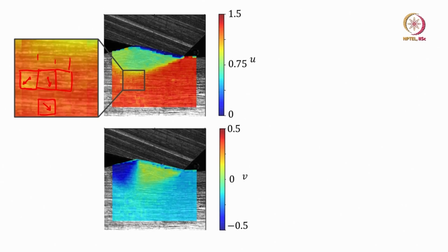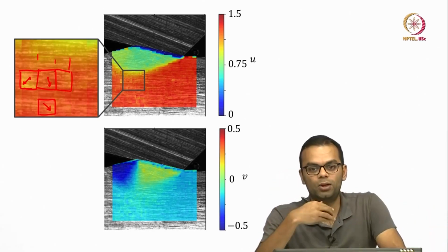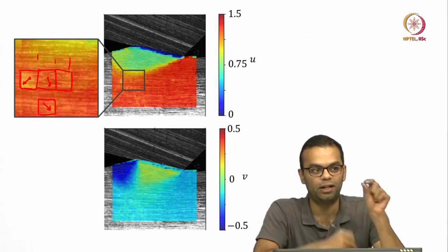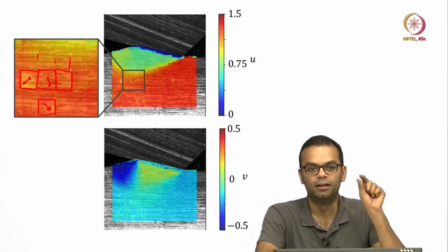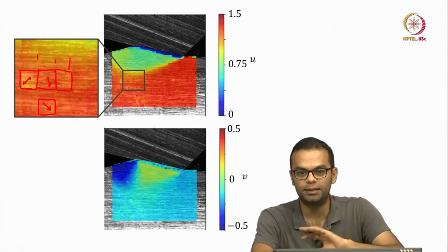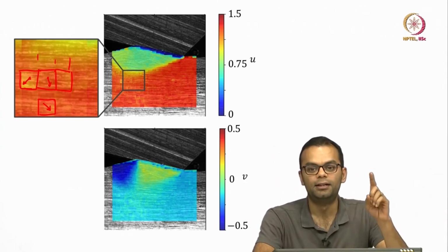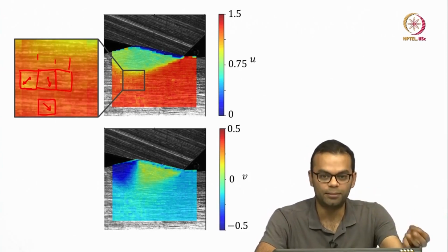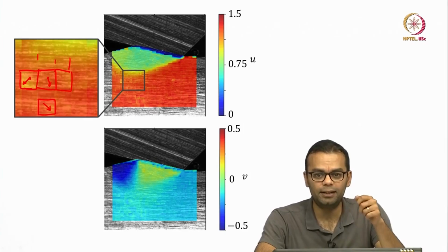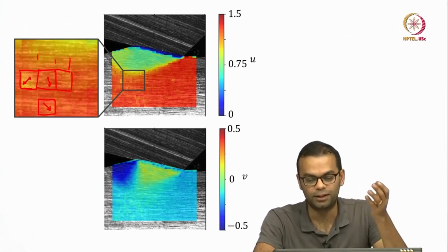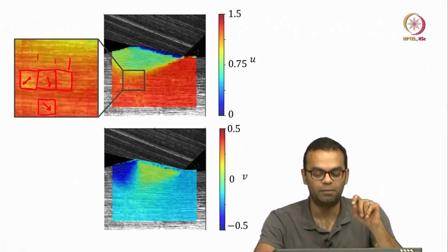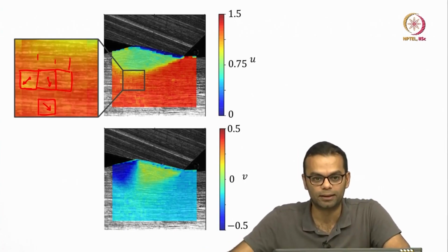Now, if you think back a little bit, there is nothing that we do to enforce that the displacement is continuous from one window to the next, right. We are only evaluating things at each grid location. We take the window there subset, we go and search for it and do our iteration scheme, get some values and we put it there. The next one we do the same thing and so on. So, there is really no guarantee that the displacements or worse the gradients will be continuous from one point to the other, right. So, you will get typically a blocky field like this everywhere.